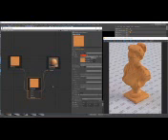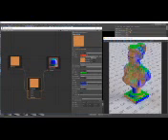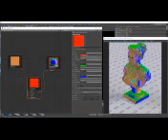And voila, the map is nicely sitting on our model without having to do any UV mapping. And the triplanar does that by projecting the map onto the geometry from all the axes and directions. In the triplanar itself, you can define separate maps for all the axes. If I disconnect the texture from the triplanar and disable this use map X for all axes, now we are basically projecting these red, green, and blue colors from different sides.